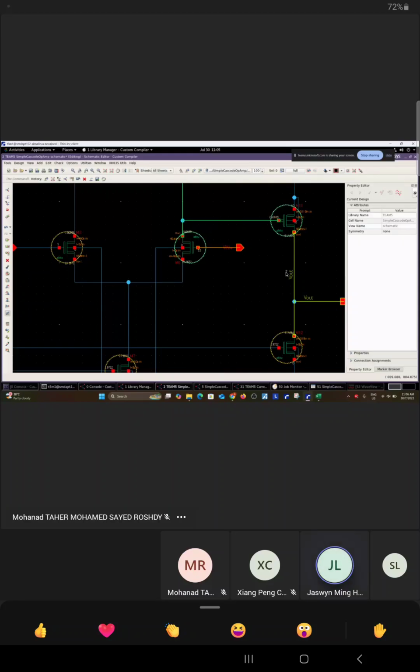So I think this only signifies your working range. Why is this in triode? Because this is inverting. The VD is so high that this voltage is very low and hits the bottom cap. That's why you see a square wave-like shape. I think your whole system is working perfectly fine, just that the range is a bit tight. How do we actually increase the range?